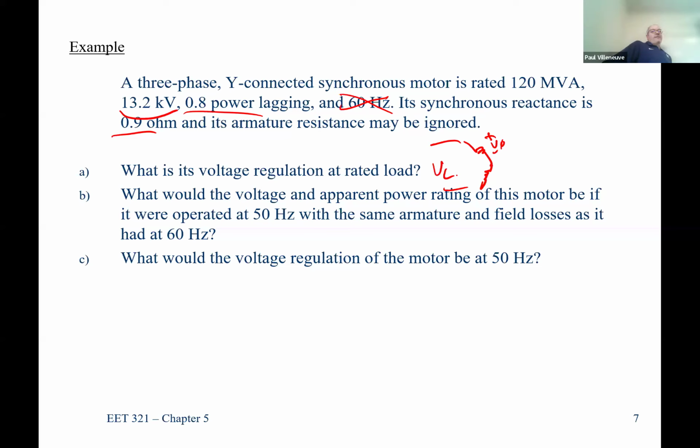No, that's okay. And the reason why I think people in industry use line voltage is because if you walked up to a transmission system and somebody told you that's a 345 kV or 345,000 volt line, you might treat it a little bit differently than if they said it was 199,000 volts. Still a lot of voltage, but one seems much, much bigger, right? Almost double the value. So if you talk about it in terms of the line-to-line voltage, that kind of tells people, hey, I have to be more aware of what's going on and what equipment to use.